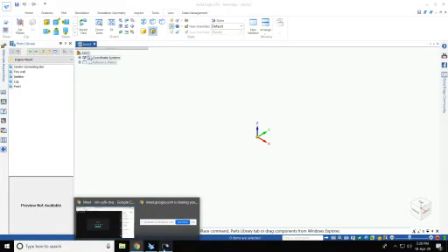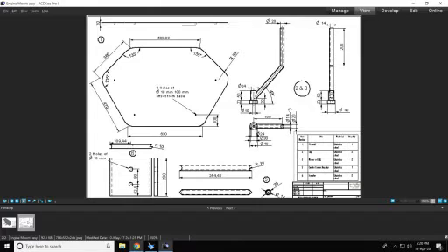Before that, you need to know some explanation here. Assembling means you assemble all of these remaining parts to their respective places where they go. The lug has a 10 diameter hole, and on the firewall you have a 10 diameter hole. Correct. So this lug will go on the firewall. This 10 diameter hole will be placed on this 10 diameter hole of the firewall, and that is where all 4 lugs go.